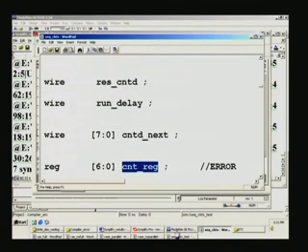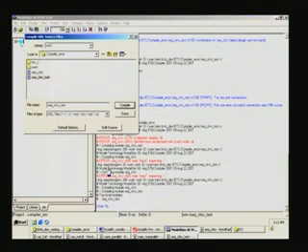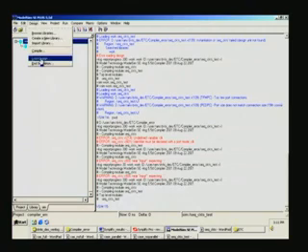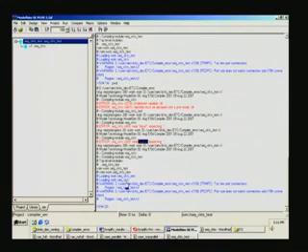And if you do this same thing in ModelSim, what will happen? It does not report any error. Perhaps it will report at the time of loading. You just load and see. It is reporting warning here. What it says is too few port connections. That is what it implied, and it is also reporting this. I think we have already seen earlier.